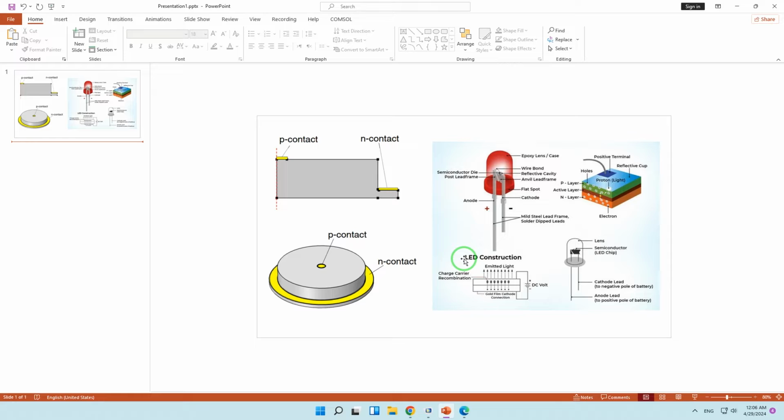The structure is made of a single p-n junction formed by a layer of p-type doping near the top surface of an otherwise n-type wafer. In this kind of device, the geometry is simple and cheap to produce, and similar LEDs are found in many household applications, for example IR emitters in TV remote controls and other controls